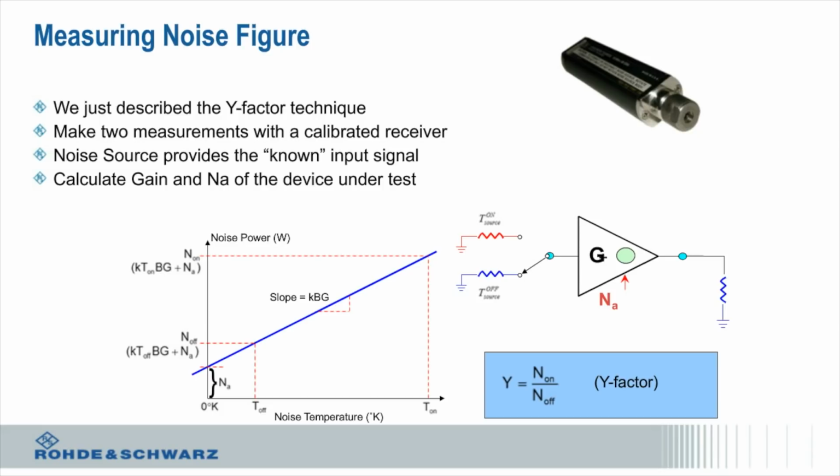So what are we doing here? Well, what we really want to know is, if I have 2 points on a gain curve for an amplifier, obviously an ideal gain of an amplifier would be a straight line with a slope determined by its gain. But if I pick 2 points off of this curve, I can determine what the noise figure added from my device is.